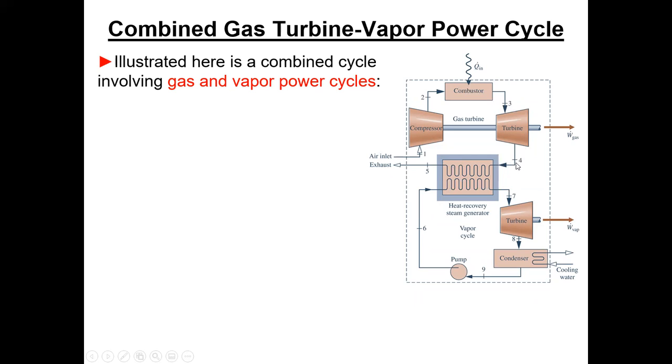We put these hot gases into this heat exchanger, basically, and it generates steam for us because we've got enough temperature and enough energy going in that we can make high temperature, high pressure steam. And then we're going to run a Rankine cycle on the low end. This would be called the high end because this is where the highest temperatures are, and this would be called the low end.